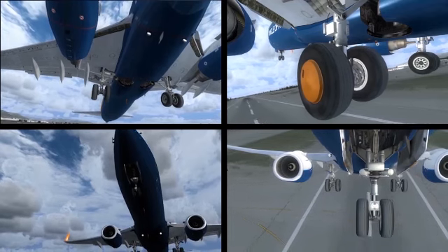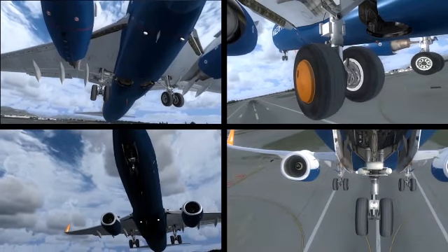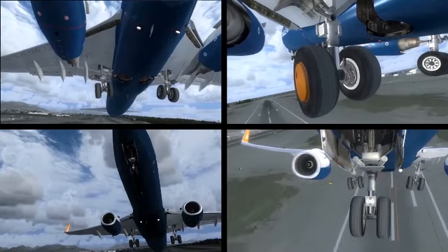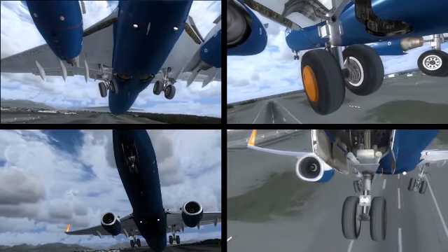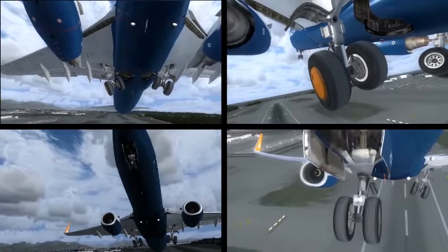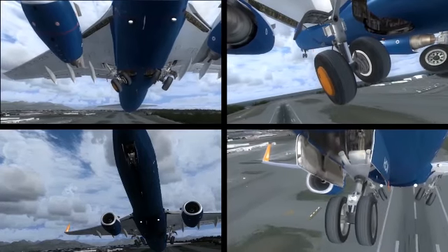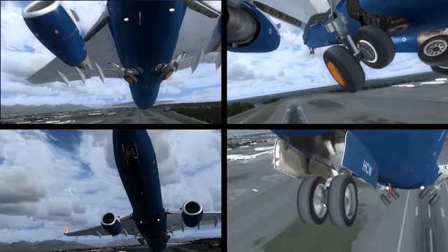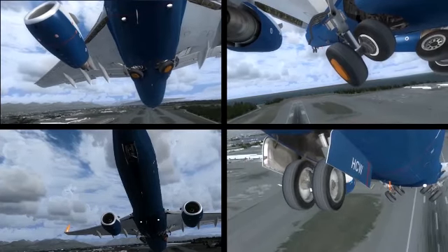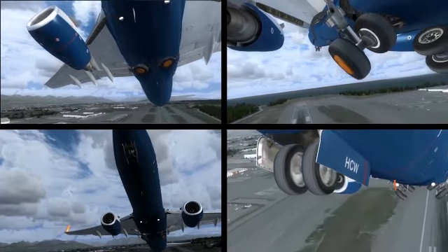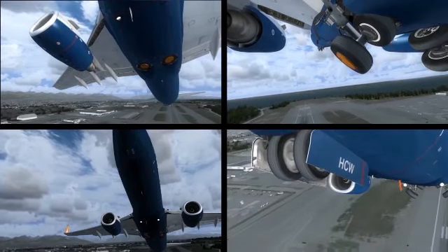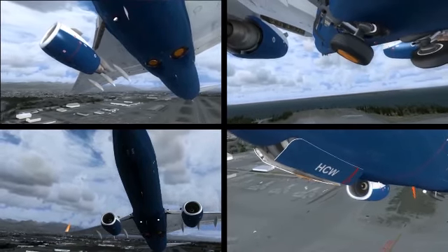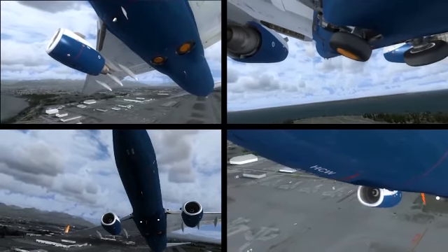Aircraft hydraulic systems are used to move control surfaces or other equipment, such as the landing gear, which are too heavy to be moved by muscle power alone. Hydraulic systems vary hugely in complexity from aircraft to aircraft, but they all revolve around one basic principle, Pascal's law. Pascal's law states that when pressure is applied to an uncompressible fluid in an enclosed container, pressure is transmitted throughout the fluid undiminished and acts equally upon every part of the container.